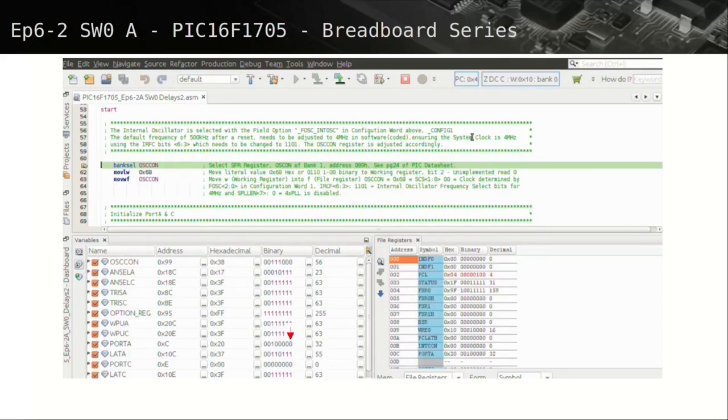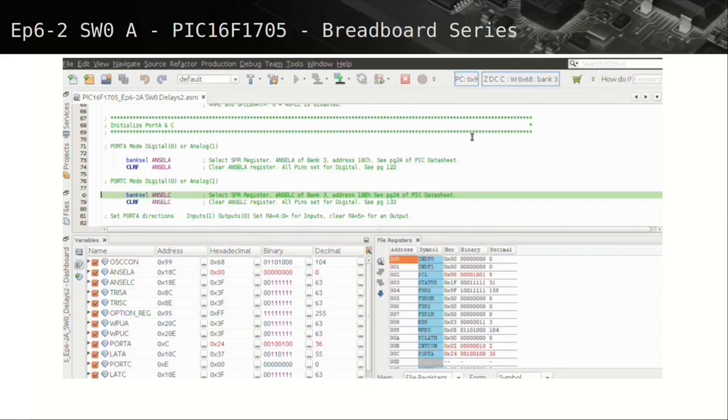Port A pins RA0, RA1, RA2 and RA4 are low due to them at this stage being in analog mode, and digital reads will be read as 0. RA3 having been set up for the MCLR function in the configuration words and its bit state indicated as 0 here. Once the ANSELA register is cleared at line 74 and the bits are read as digital, RA2 is now reflected as being high as expected, as it is connected to the 5 volt VCC through the 10K resistor, so pulled high until the connected switch is pressed and pulls voltage low.